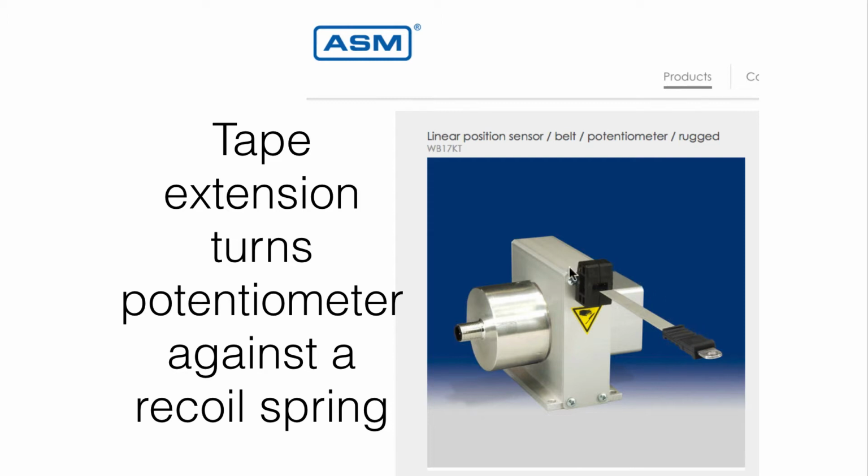Now, this has got the considerable advantage that if your extension is maybe up to a meter, you don't need a measurement device that's a meter long. You've got this tape that's pulling out and going back in. So, although we'll work in the lab just with a rotary potentiometer and measure rotary position, it's important to keep in mind that these things are commonly used to measure linear position, which is something that we're often interested in from a mechanical engineering standpoint.